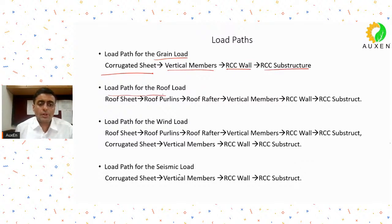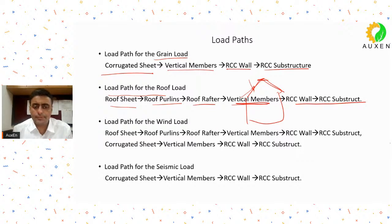Whatever load you have on the roof, you remember you had this type of roof. So whatever load you have on the roof, of course, easy, that will be transferred to the roof sheet, from there to purlins, from there to rafter, from rafter to vertical members and substructure. Same load path for the wind also.